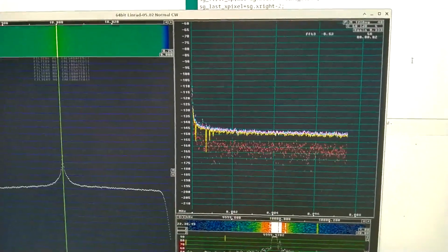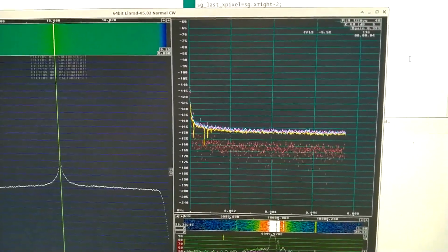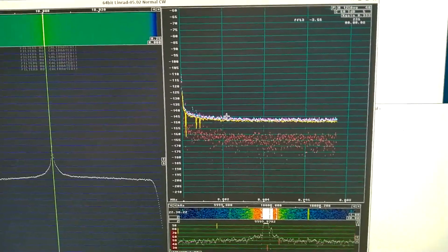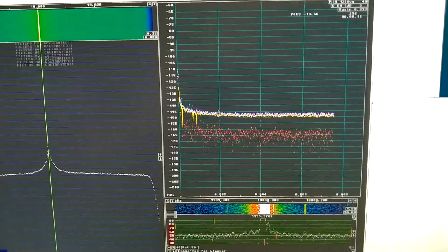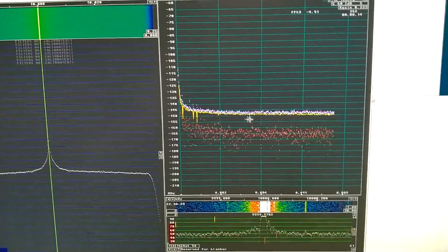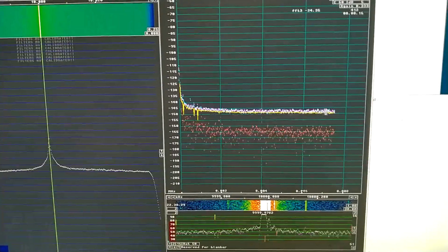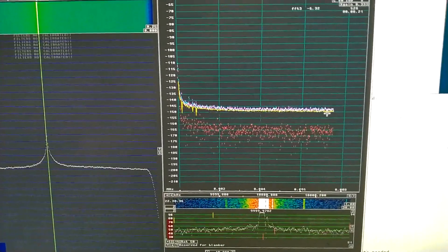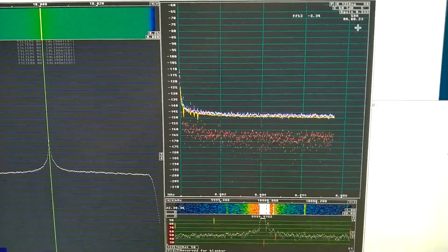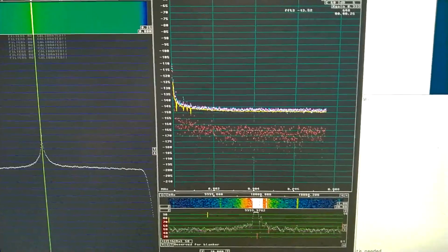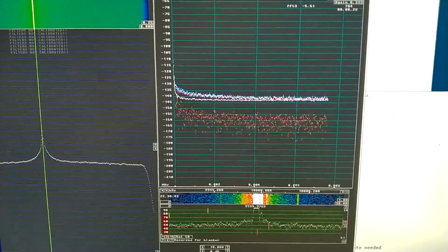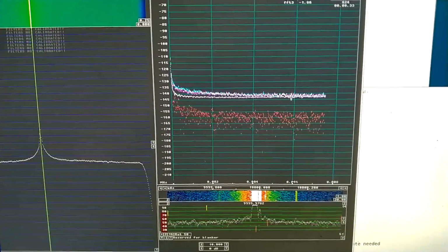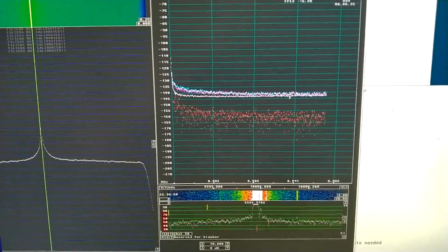I have a setup where I collect the phase noise rapidly. The yellow trace here is the phase noise up to about 7 kHz. It is around minus 150 dBc per hertz. And the statistics is already very good after 30 seconds. I can look at the amplitude noise. It is here. And it is also very good statistics at the same short time.